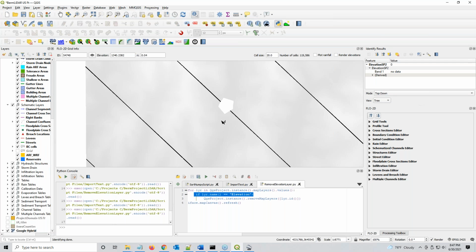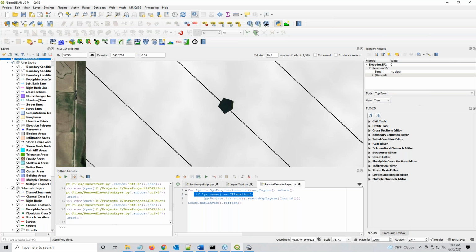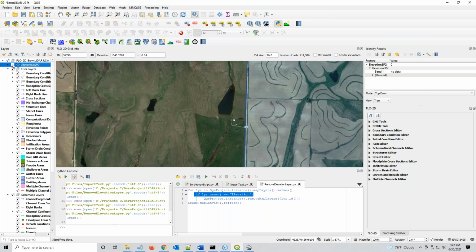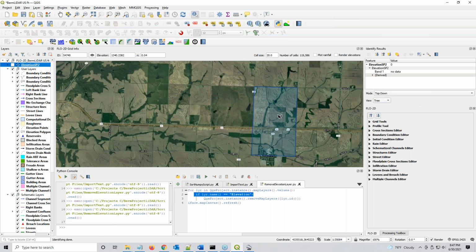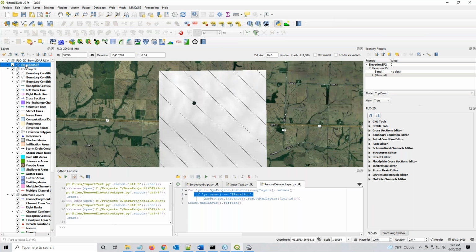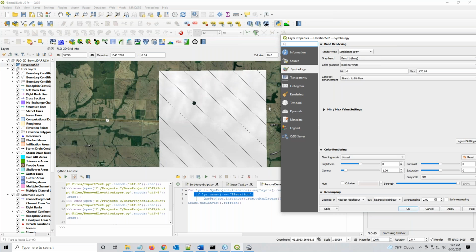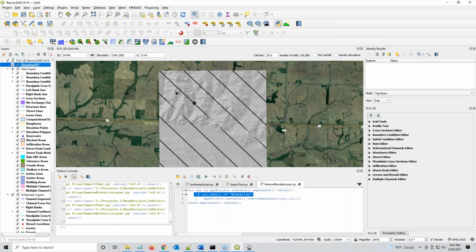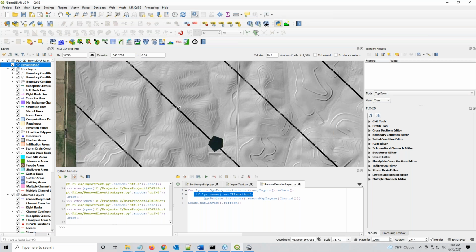some of the stuff is missing, because there's certain things in LiDAR data that's missing. So you might need to do an elevation patch if you have a big piece of data that's missing. There's probably a way to fill no data if you look into the LAStools, so you wouldn't have to worry about that. But in order to get those vertical lines out, you'll definitely have to purchase it. And the hillshade, let's take a quick look, and you can see that it's just beautiful data. Except for those vertical lines, it's just perfect, excellent data.